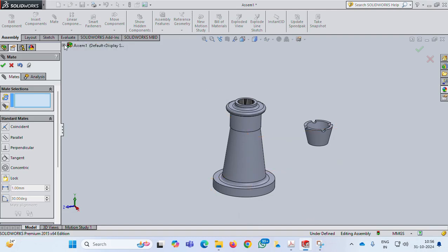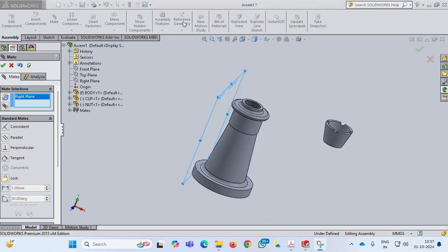Next, you select the front plane. First, this is the assembly workbench, and we have three planes for this workbench, that is front plane, top plane and right plane. And for every component we are inserting, that component is also having three planes, front plane, top plane and right plane. For the perfect assembly, I want to coincide all the planes with respect to the assembly workbench planes.